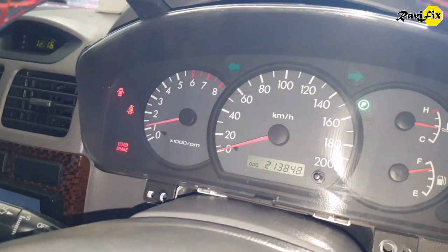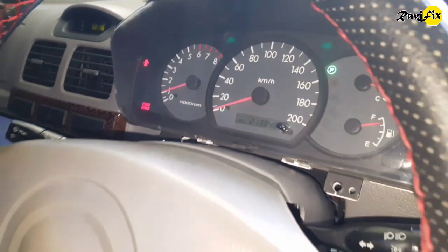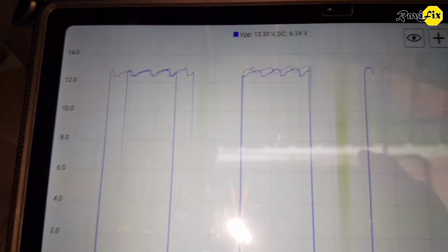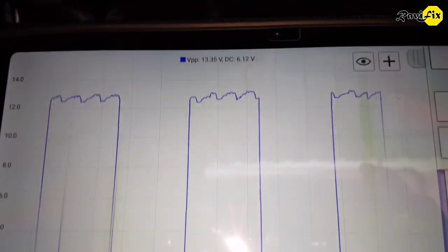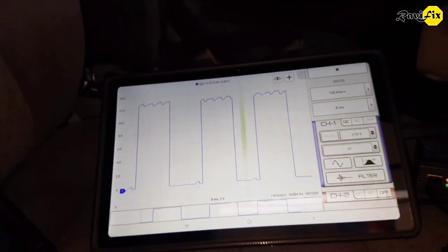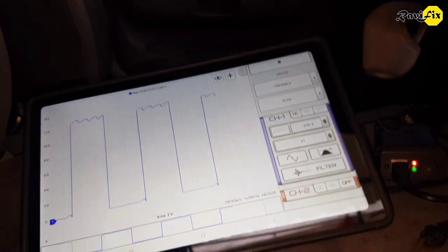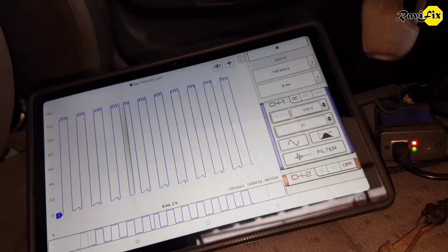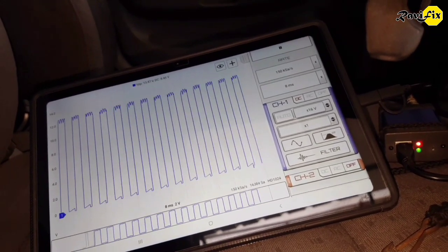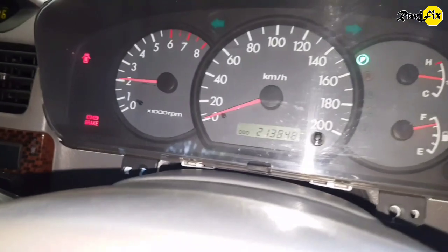Wow, look at that. The tachometer comes into action. That means we have shot the trouble. Okay, let's get into the RPM signal waveform. Look at that, it has battery voltage as it should. So a bad TCM was the problem. The TCM pulled the signal to ground. Beautiful, the tachometer is working perfectly.